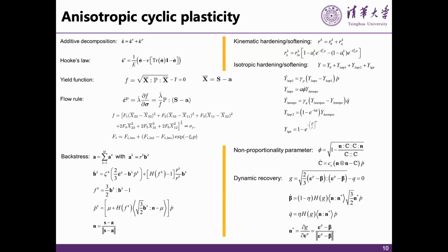The question is how to develop the stress strain constitutive model. We have a cyclic plasticity model based on one consideration: we changed the yield condition, that is, the yield function f. We introduce weights according to the Hill method. We assume the weight function is a function of plastic strain to apply it to cyclic plasticity. That means F1, F2, F3, and F7 are not constant. They are functions of plastic strain. That's just empirical, phenomenological fitting.